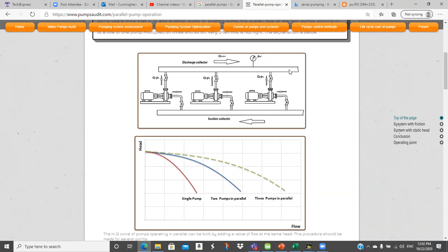So this can be a big pipe. This could be 10, 12, 14, 16, 18 inches, and these could be very large pumps. This could be like a cooling water loop that's going to a bunch of machines that have to be water cooled. Air compressors are sometimes water cooled, and just all sorts of heat transfer furnaces, and arc welding equipment sometimes has to be water cooled, and there's lots of reasons. Lots of manufacturing equipment has to have some sort of cooling, and water cooling is usually more effective for the heat transfer than air cooling.